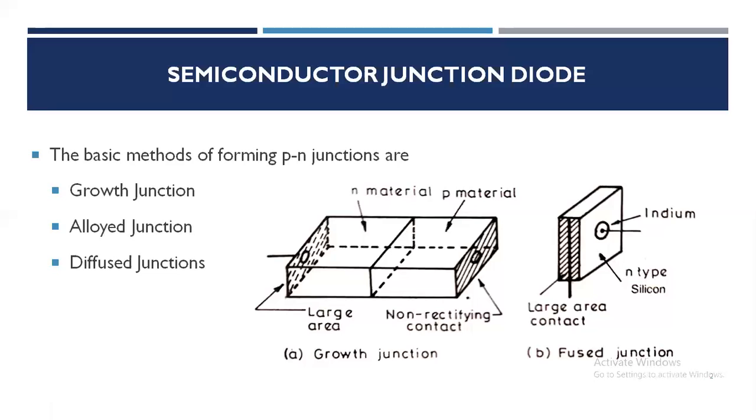When this combination is inserted in an oven for several minutes at a suitably high temperature, the indium fuses to the surface of the silicon and produces p-type silicon immediately below the surface. Thus, a PN junction is formed between this P region and the main body of the N-type silicon wafer.